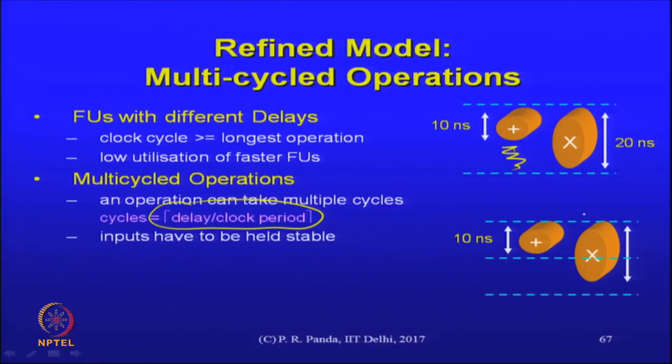Since this is taking multiple cycles, of course the processing is incomplete at the end of the first cycle, you need multiple cycles. Which means that if they came from a register, then that register cannot be reused for the duration of this operation. And if they are coming directly from another operation, then they need to be stored in a register. If they came directly from some other operation, this falls into the standard requirement that I have a dependent incoming edge which crossed a clock cycle boundary, right. This previous clock cycle boundary is what it crossed. Therefore, you need a register for it.